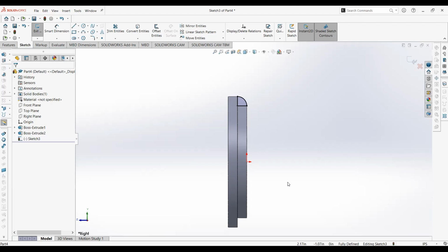Okay, everyone get on this. Okay, well, first we sketch. So hit right plane, and then hit sketch. Okay, so hit that line. Convert entities. And then hit the top line and do the same. Yeah. And then draw that arc. And trim that extra.